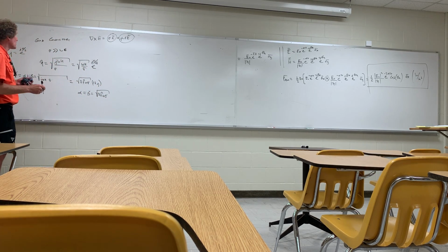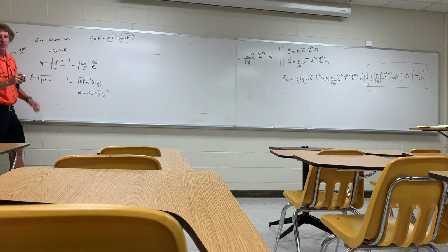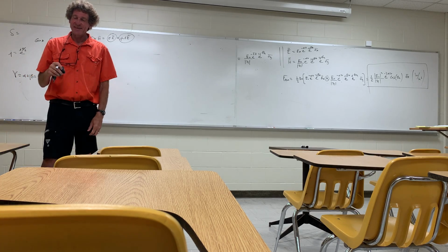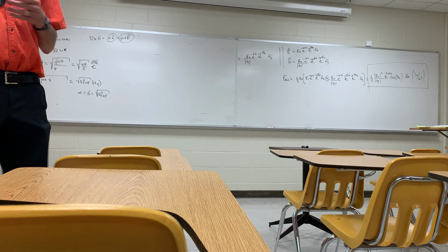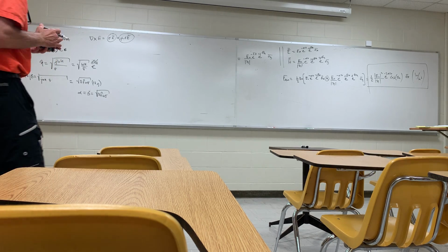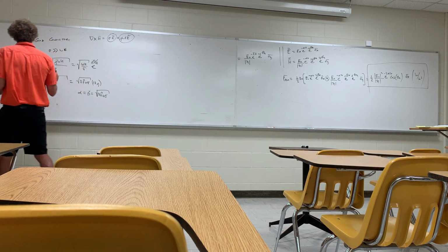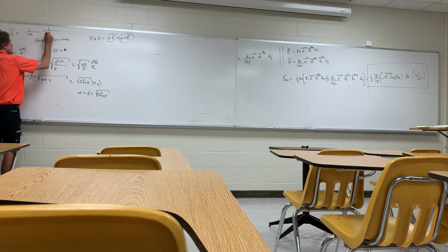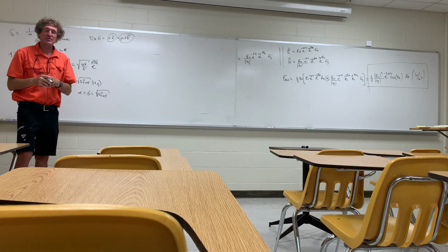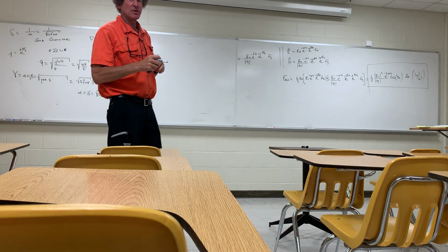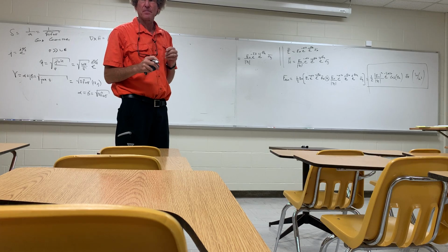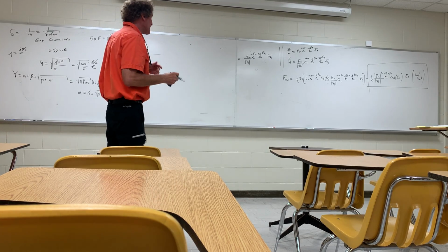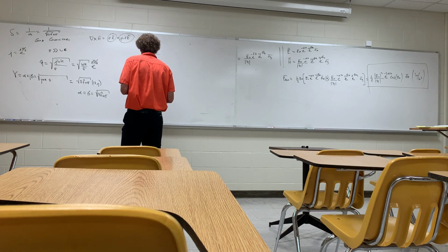Remember this? Now if you've done your homework, I hope you have, do you remember this term? What is that called? And I don't mean something to do with a lost end. Skin depth. It's skin depth, right? What is skin depth? Well, skin depth fundamentally is just 1 over alpha, and it's equal to 1 over the square root of pi f mu sigma. Remember that. Those are things that should be almost automatic. You shouldn't even have to think about it. For a good conductor, this is the way it is. If you keep up with the homework, you will probably get to that point without much trouble.